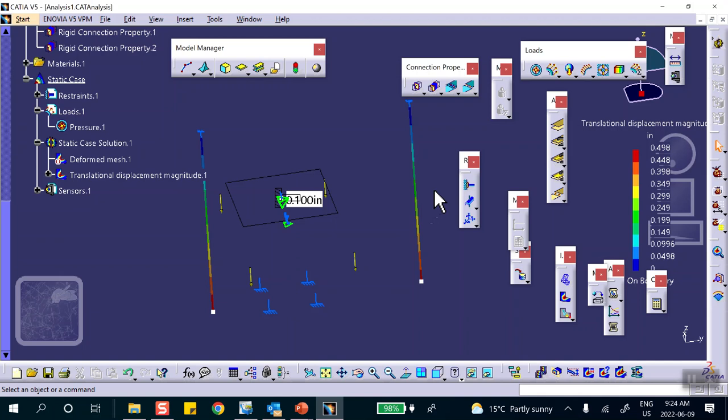Very good. On the sheet, right? Symmetry from the sheet. Remember, one thing we know: if this was cut like that, it doesn't move this way. If this is direction, for example, y, no displacement in y, rotation z, rotation x 0. Because, what? Sorry. Yes, yes. You have no choice with beams and shells. You have to use user-defined constraints. Okay. Stop this.